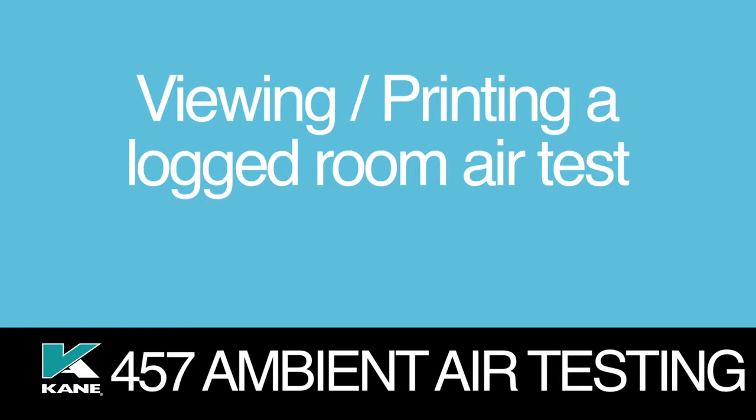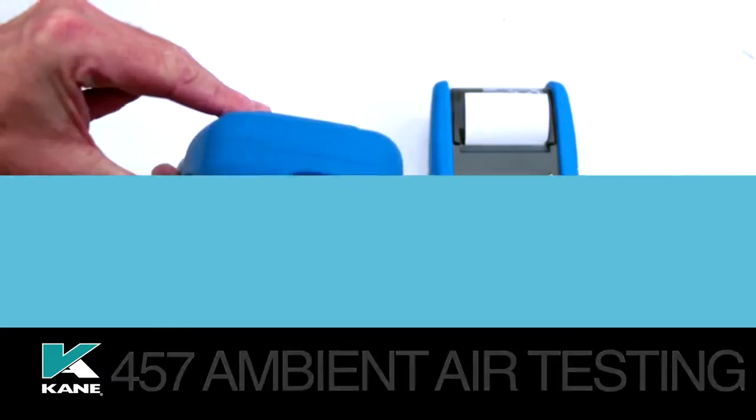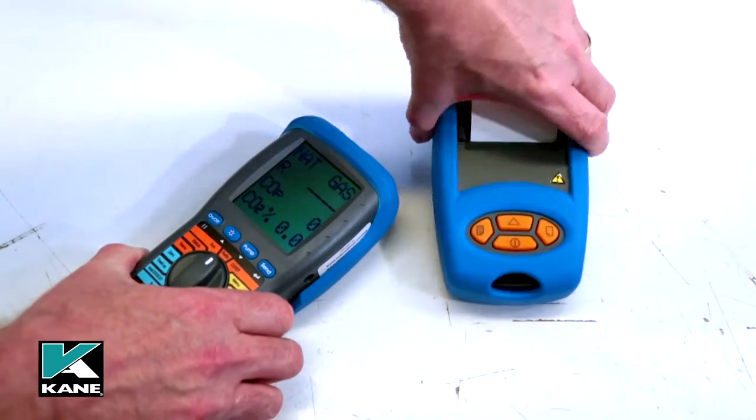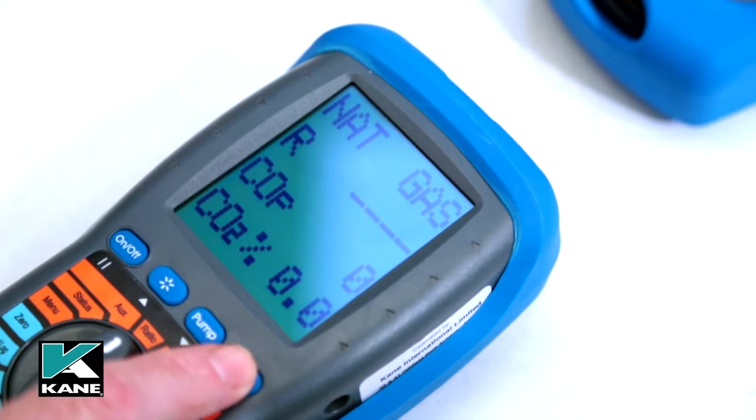Viewing and printing a logged room air test. Select Menu, Report, Room Air, View. Use the up or down keys to select the log number to be printed. Press send to print the test or send to PC or Android device via optional Bluetooth connection.